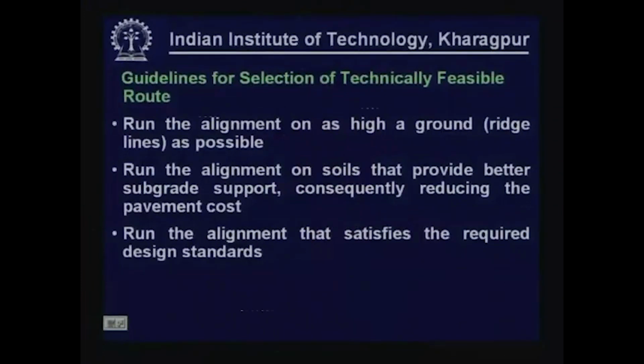Run the alignment on as high a ground as possible. Basically, try to take the ridge line. It will obviously be beneficial from the drainage point of view, and there are several other advantages.